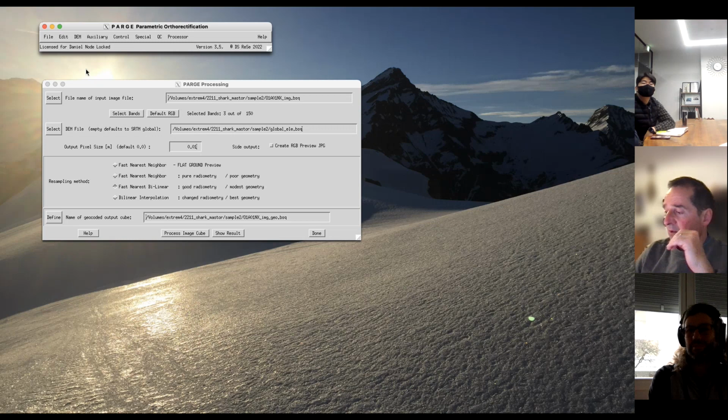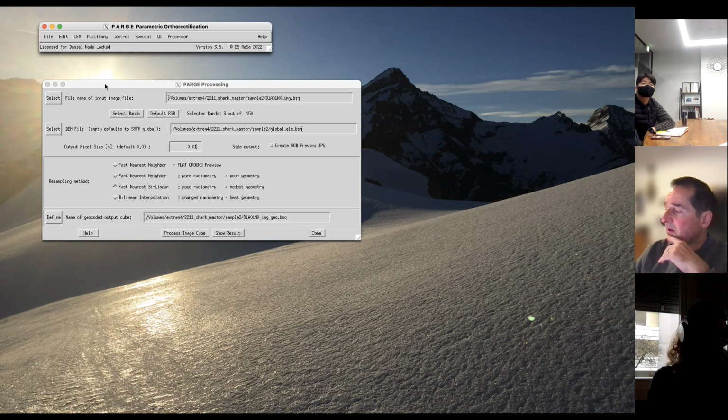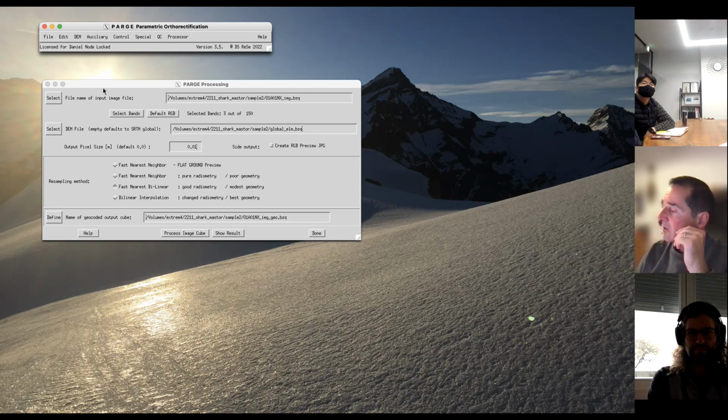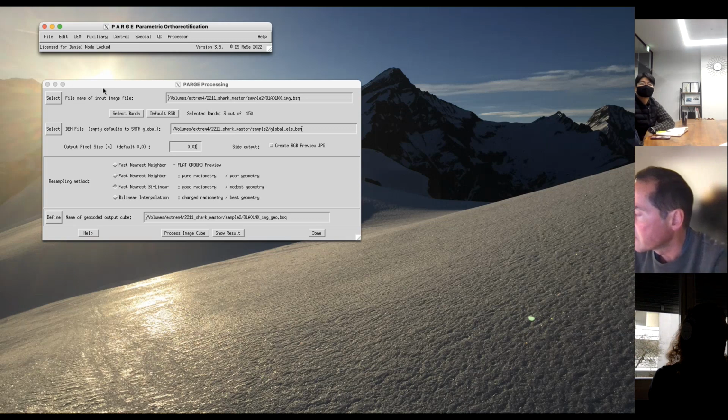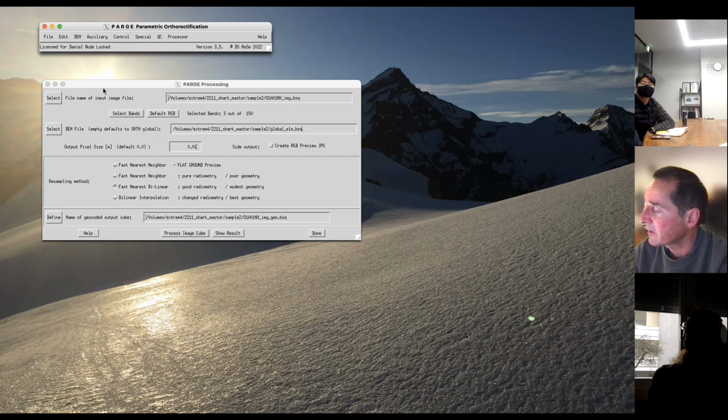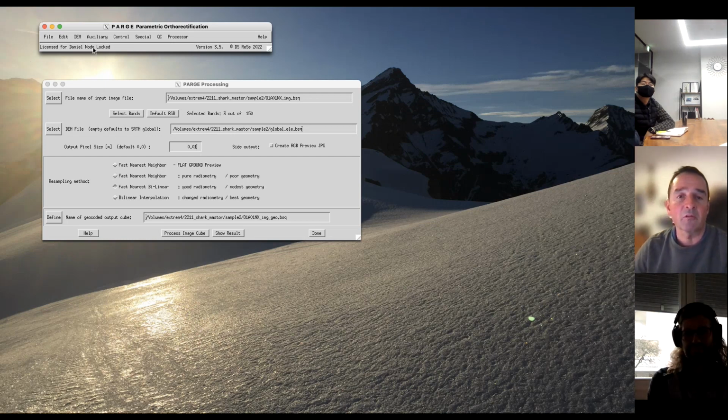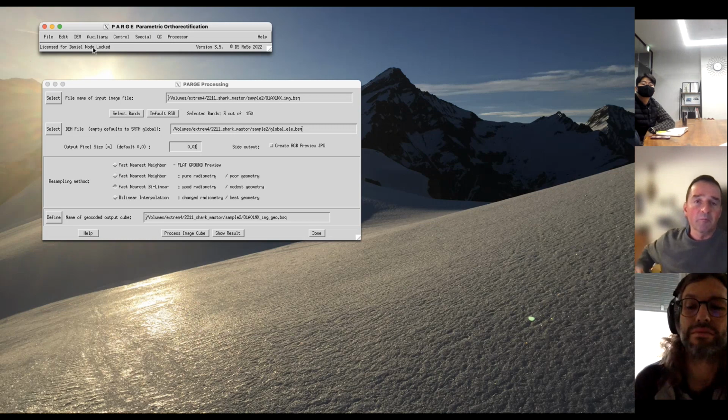And so if you want to do a good bore sighting, you should fly your system once in a while over some settlements or some roads, such that it's stable. You have good structures to do a matching between an orthophoto and your system. Usually, the so-called bore sighting is only to be done once in a while, so every few years. So if you once have a good bore sighting, you wouldn't need to change it. So that's not to be done every time. So that's what the problem is, to get a good one once.